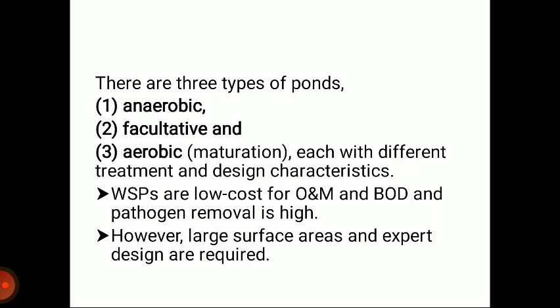There are three types of ponds: anaerobic, facultative, and aerobic, each with different treatment and design characteristics. WSPs are low cost for O and M, and BOD and pathogen removal is high. However, large surface areas and expert design are required.